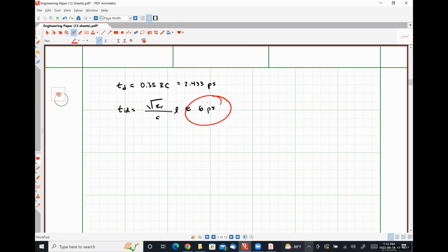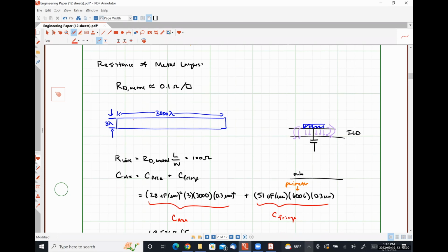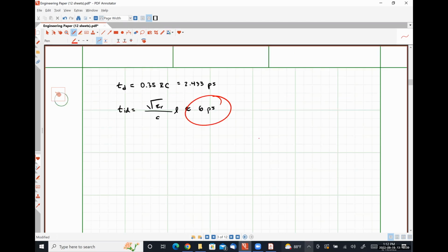We do at times have to worry about the resistive losses and things like that, which we can largely mitigate by just making our metal runs wider, right? So if we need to get a signal 3,000 lambda away, we can make this half as resistive by doubling the width and so forth.